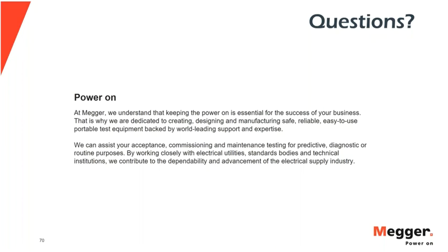today, and this is really important, I've been triggered to do the testing by some kind of alert, and so the transformer just comes offline, and I'm right in there testing it, so maybe the top oil temperature is like 45 degrees C when I'm doing my test. Well, the expectation is that just because of the temperature alone, I'm going to be measuring a higher power factor. So say, in fact, I do measure this higher power factor, and my power factor before was 0.3%, and now it's 0.68%.